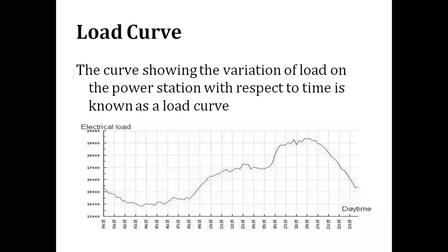Now, what do power engineers or the PDD department engineers do? Firstly, they make this load curve on a daily basis. For example, if we take the year 2020 in the month of October, on the very first of October, the power engineers made this load curve.